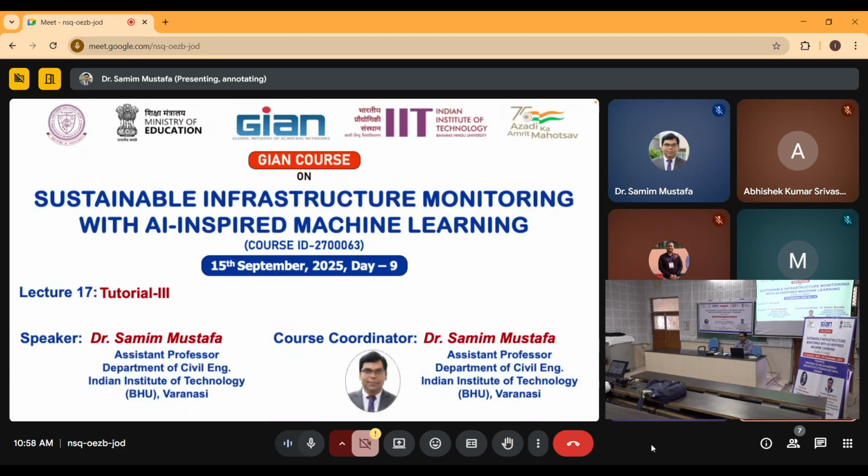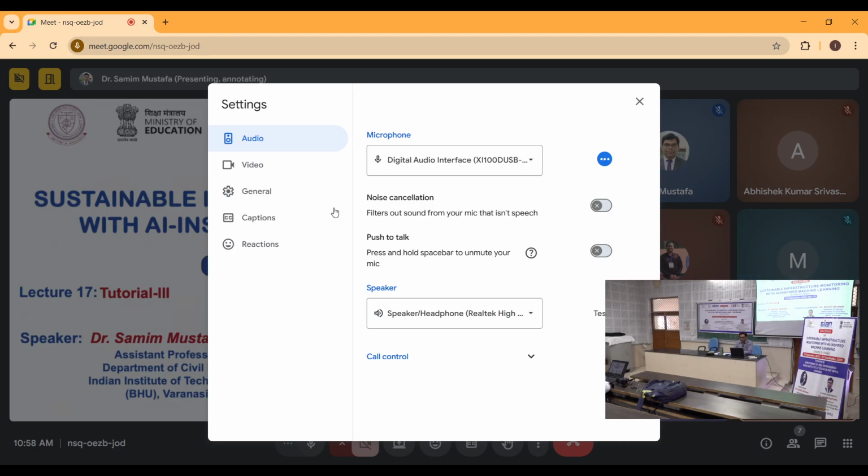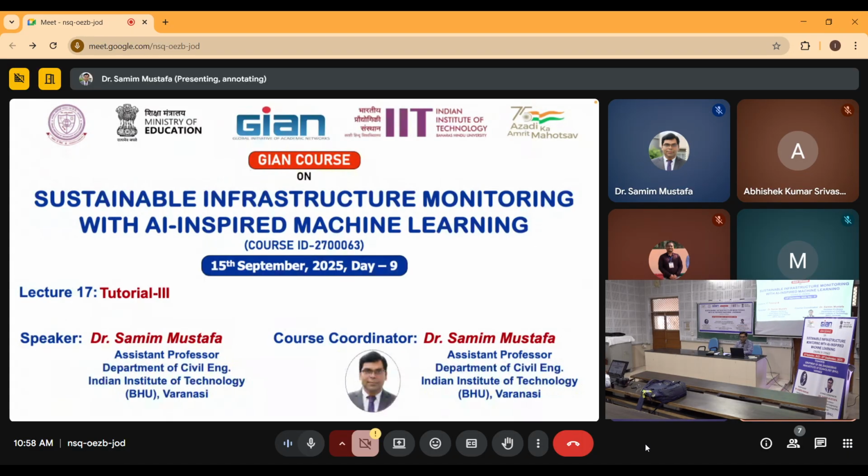Because you need to measure the response from the structure using a sensor, it is inevitable that there will be some noise in the sensor data. So you have to deal with filtering, right? It should be useful to you if you know how to filter the data. In general we use a high pass or low pass filter depending on the nature of the data and what response we want to keep and what response we want to discard.